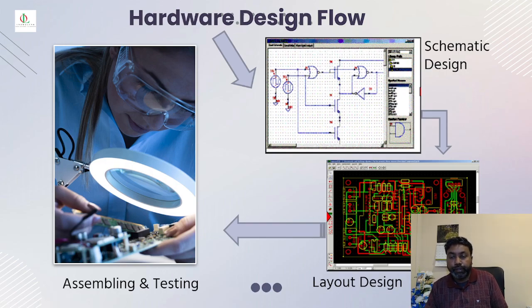That really is helpful. Once all the logic design requirement specifications are met, you generate files for assembly people to make the board for you for prototype testing. It's called a Gerber file, so you give that to the manufacturing company and they will make the board for you.